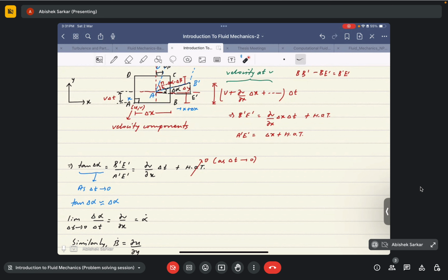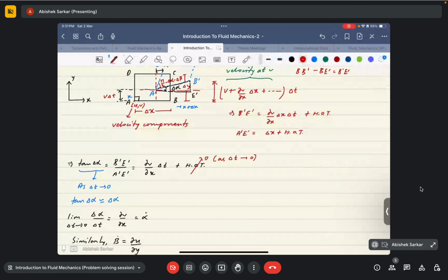Because in the case of solids, Hooke's law tells us that the net stress is directly proportional to the net strain in the body up till the elastic limit, right? But in the case of fluid, if we consider a Newtonian fluid, then from Newton's law of viscosity, tau is equal to mu epsilon. If we consider a stress tensor, tau ij is equal to 2 mu eij, and this term eij in essence is actually the rate of strain rather than the total strain. Okay, it's actually the rate of strain or the strain rate.